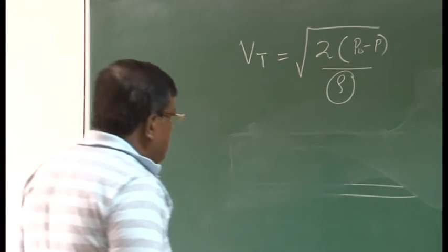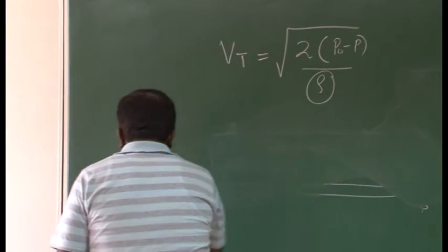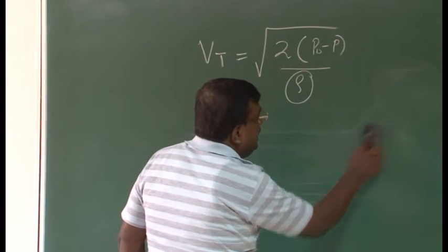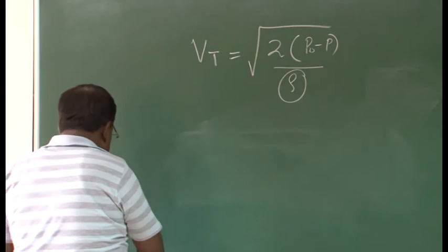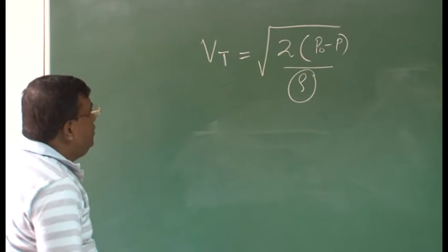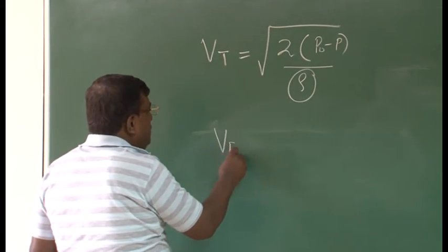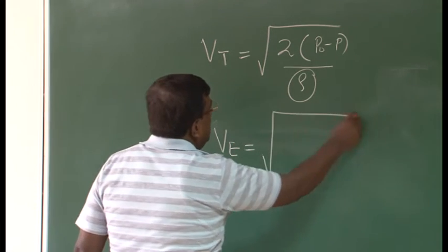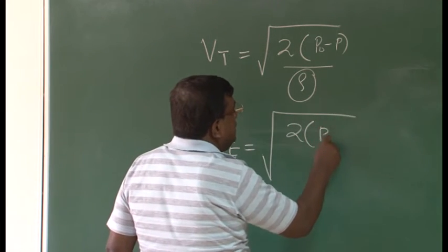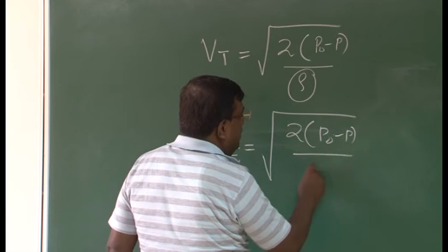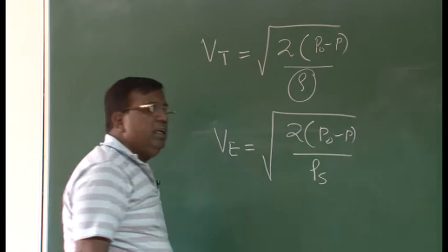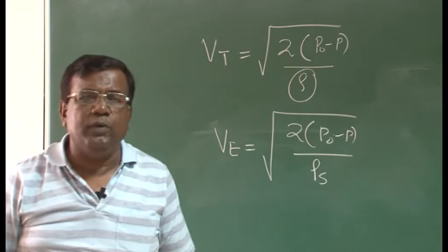But for calibration purpose, you could understand that for every altitude getting density and all, calibration will be a difficult thing. So we have defined some speed V where this is the same dynamic pressure, however rho is rho s, which is the sea level standard atmosphere value.